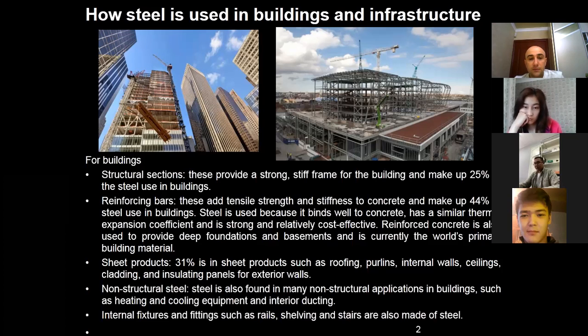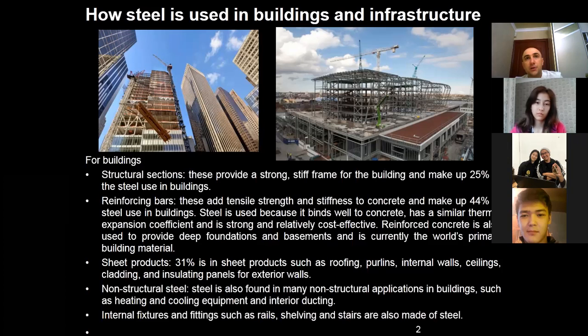What else? Steel has a higher expansion rate when the temperature is changing. So when there is a quickly changeable climate, it may be possible to use some protection layers which will protect steel from direct cooling or direct heating, so we need to protect it.